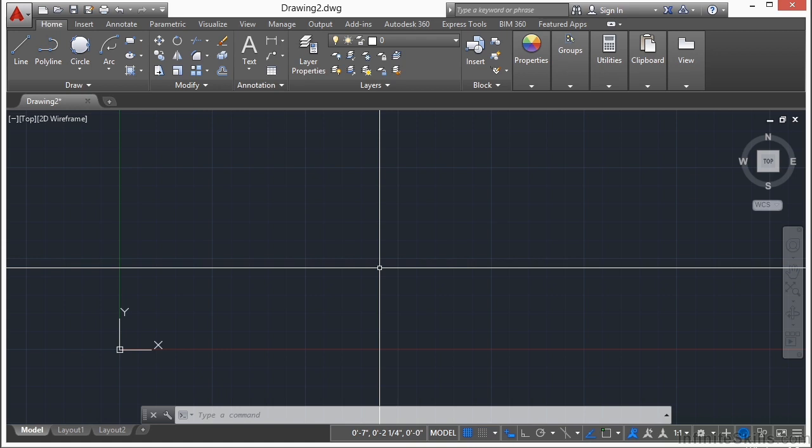Now it's one thing to be able to draw lines and circles, but it's another to draw them accurately. O-snaps are one of the key features in AutoCAD that enable us to be able to draw with precise and exact accuracy. O-snap is short for object snap. They force you to automatically draw from a specific point on an object. We've used several of them already, like endpoint, midpoint, or center, or even the nodes. But I just want to make sure that you get an introduction to them, as well as some of the other methods of drafting that we have.